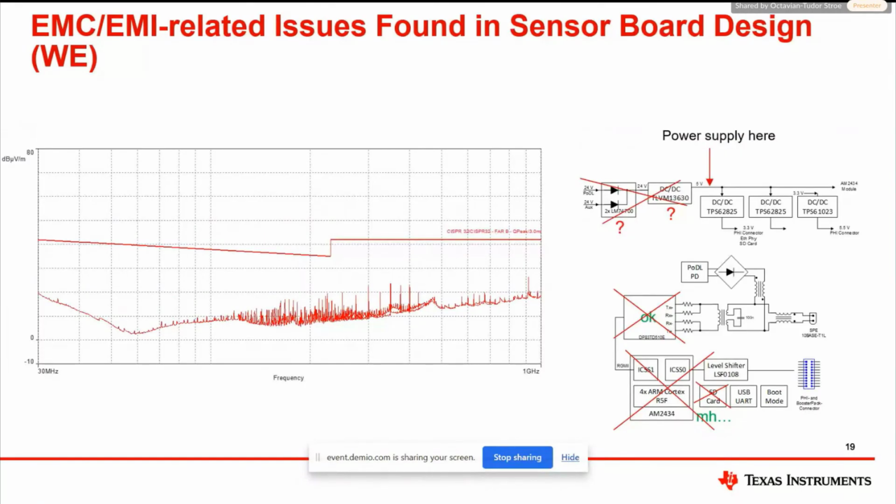The small DC to DCs are very clean, even though they're operating at 1 megahertz and have rise times in the range of 1 to 2 nanoseconds. On the switch node, we can see it's quiet as a whistle. So now we identified what makes most of the noise.